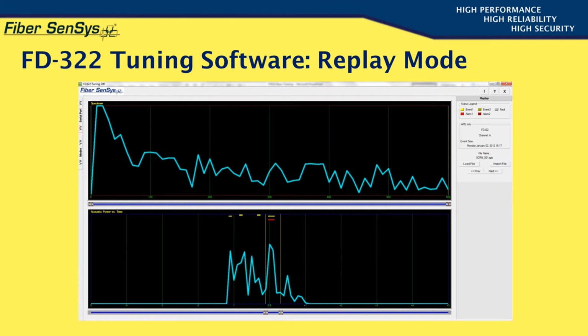The replay mode allows retrieval of spectral data files from the PC's hard disk and displays both frequency and time domain representations of a data file simultaneously. The recalled time domain data is displayed in a 10-second window at the bottom of the screen, showing the trigger event plus 5 seconds before and 5 seconds after. Color-coded symbols representing alarms and events from the cut and climb processors are displayed on the time domain waveform at the times of their occurrence.